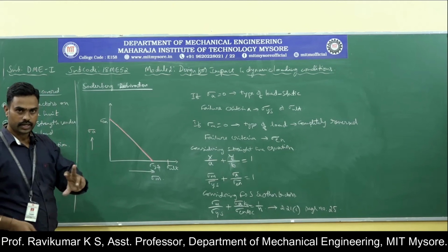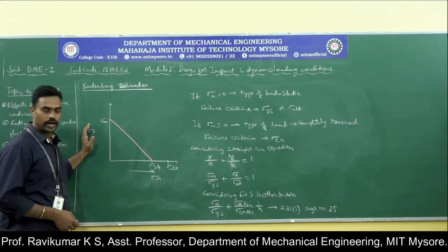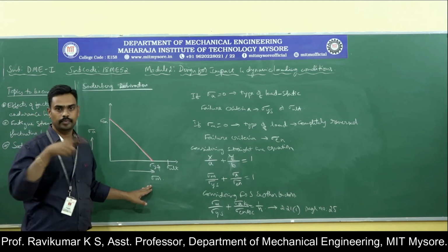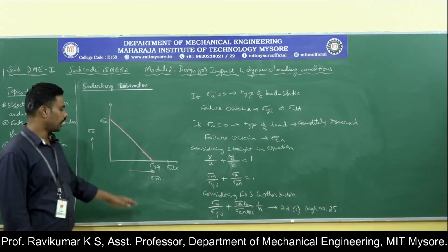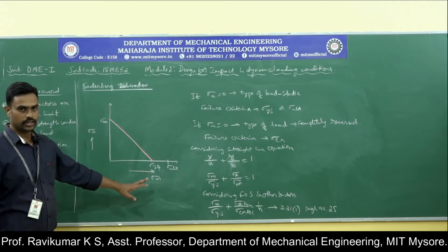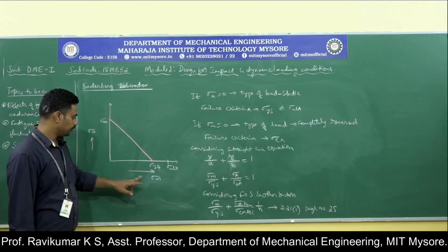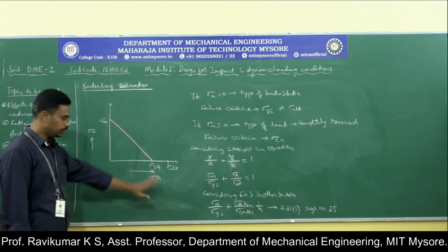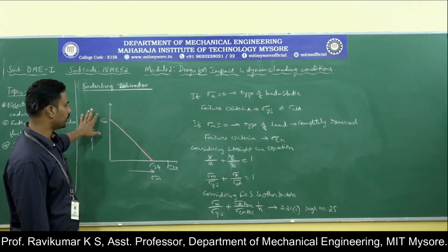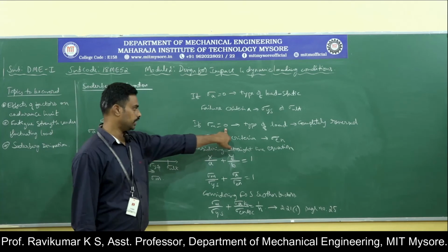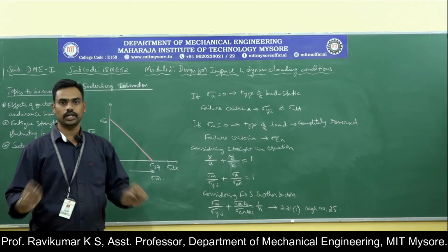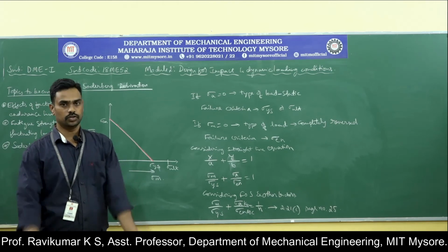Whenever you find the cycles, there will be amplitude, therefore you will find amplitude stress, that is the cause, and since there is an amplitude, there will be mean. So mean stress I consider in the x-axis. Similarly, as explained in the previous session, if the mean stress is 0, then the criteria will be completely reversed. Look at here, if the mean stress is 0, then the type of loading is completely reversed. So in the completely reversed cycle, you will find mean stress is equal to 0.